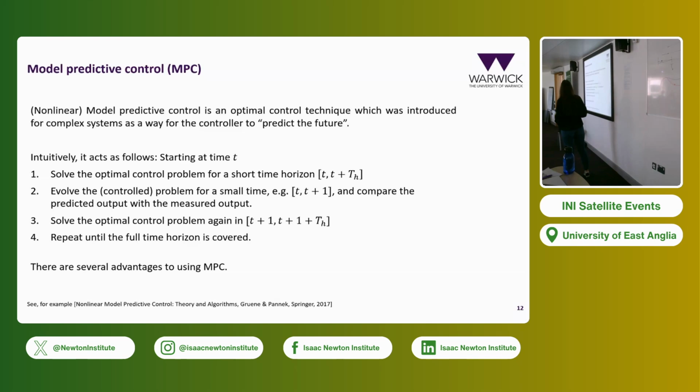And what we decided to do in our problem was, okay, let's do the same. Let's solve the optimal control for the weighted residuals model, and then apply the control to the DNS. Instead of deciding we're going to do t to t plus 1 or something like that, we said there's a model error that can be big between the DNS and the model. Whenever the difference between what we predict with the model and what the DNS is doing is big enough, and big enough is whatever we want it to be, we solve the optimization problem again. The advantage is that because you already have the previous solution, we already have a pretty good guess of what the control is going to be. So the optimization is not going to be very hard. You don't have to do a lot of iterations because you already have a very good first guess.